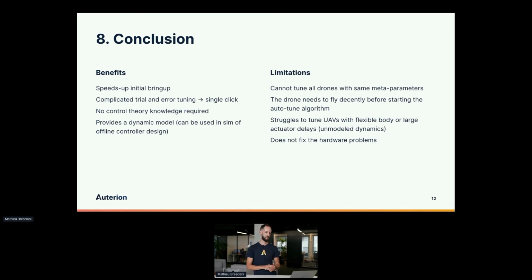and then you can get a worse result out of it. And the most important one is that, unfortunately, it doesn't fix your hardware problems. So if you have a lot of vibrations, maybe the resulting control will be too aggressive for you, and you will see some vibrations. It cannot deal, for example, with huge delay. If you have a lot of delay in your control loop, that won't fix it. It will try to do its best to reduce the gain, to have it flying, but it won't fix everything. But it should give you a good base tuning for most platforms.